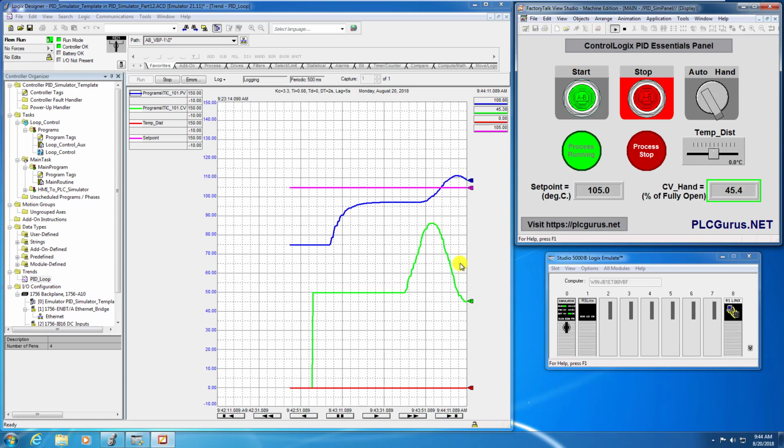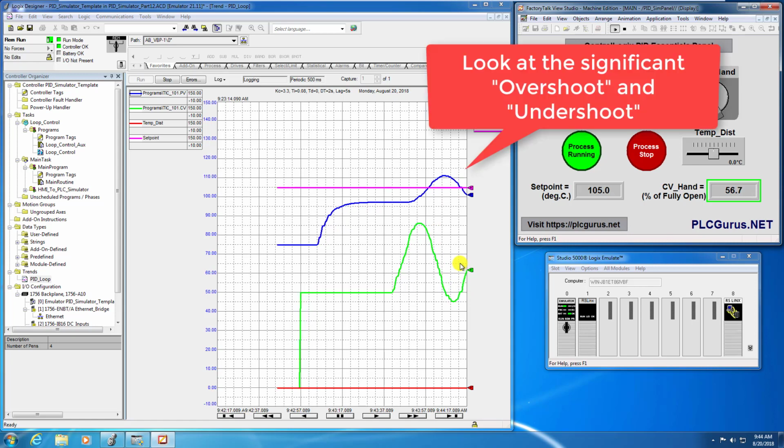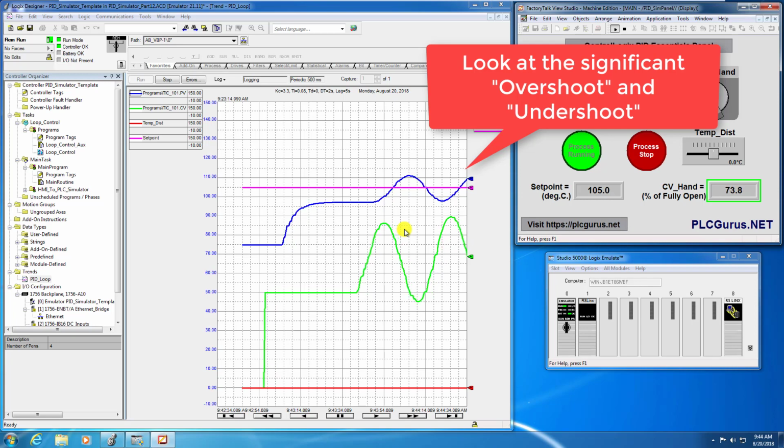So we're compensating by moving the valve because we're seeing the temperature isn't changing straight away, and we're overcompensating. So this is what we're seeing here. See how we're overcompensating here? Because we're not seeing what the impact of adding more steam had on our process. And that's why dead time is a very, very bad thing, because we are changing the output but not seeing what the result or the impact of that change was.